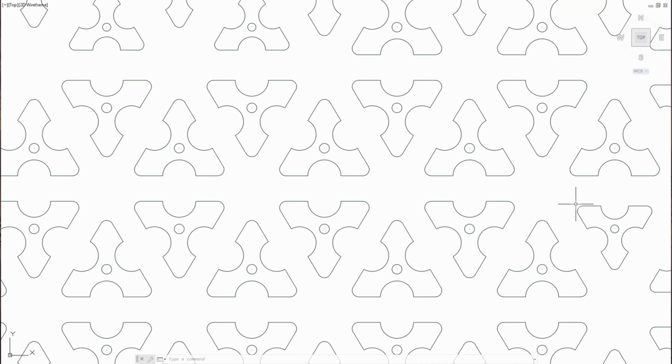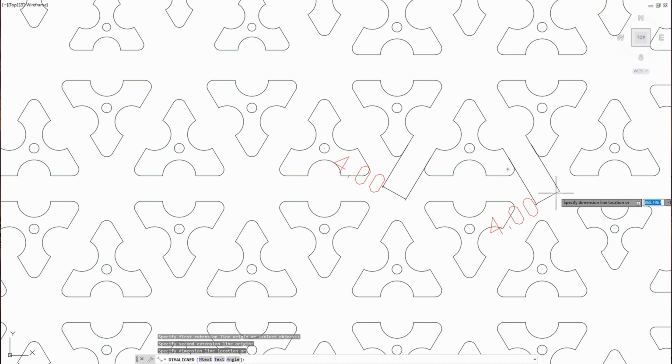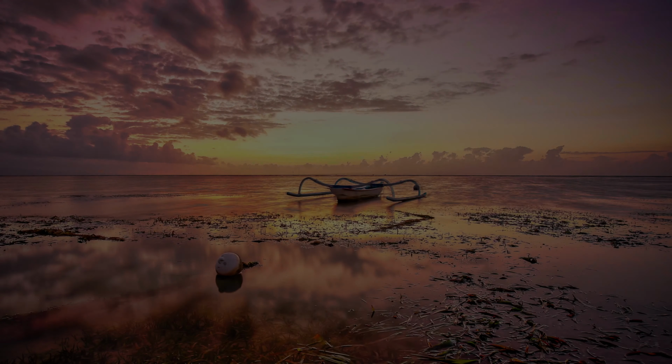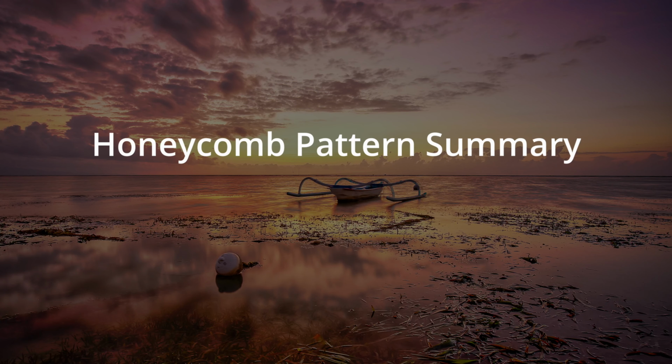From here we can also see that the minimum gap is satisfied even though the largest tool is the non-ideal shape. However, if we use the non-ideal tool and let Image2Punch calculate the inscribed diameter automatically, the perforated pattern result will have an incorrect minimum gap, as we can see here where the minimum gap is less than 5 mm.